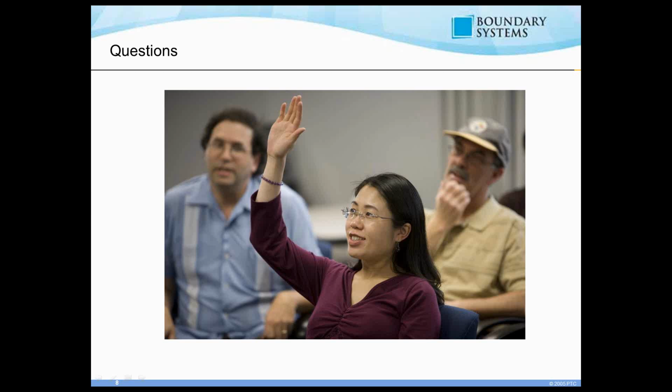Another question I had in here is, is it possible to tell Model Check to skip certain models? By that we mean, say for example, we typically make models A and B, and models A we want to enforce, and models B we do not want to enforce with Model Check. Model Check has a built-in parameter functionality where you can put in a particular parameter, and when Model Check reads that in, it recognizes that it does not have to analyze that particular model.